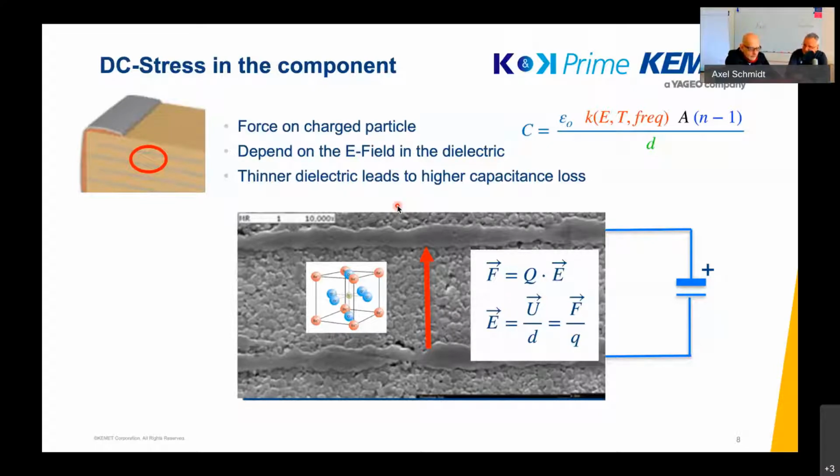If you look at the upper right formula, if I have a 1 microfarad capacitor with nearly the same voltage range, going from 0805 and 0603 down to 0402, the only way is to change my dielectric thickness. That increases the capacitance, and I can stack more layers inside the smaller area. That's how all manufacturers put higher capacitance values into smaller case sizes. But if you thin out the dielectric, you increase the effect. That means smaller components with the same cap values typically have a worse DC bias than bigger components like 0805, 1206, or 1210.